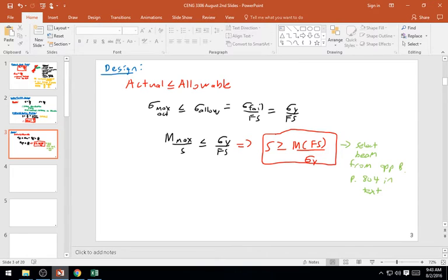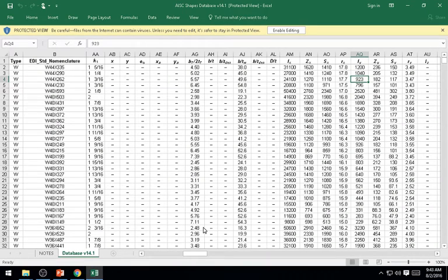In other words, if you have a beam here that is like this, your normal vertical loading is going to be strong axis bending along your XX axis, because that generates stress along the XX axis. Your weak axis bending would be if you have lateral loads coming in from the side, and certain shapes are better at resisting that than others. But generally, the shapes obviously have a strong and a weak axis, and you can see that here.